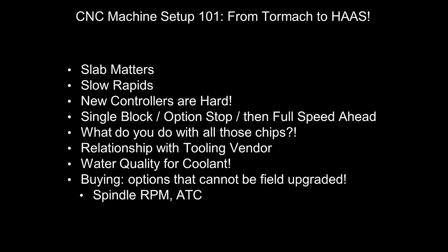But again, I'm very glad you brought up the work holding. People often forget how important it is and how easy it is to throw apart or pull a tool out of the collet chuck, all these sorts of things. Yeah, and that's kind of increase in power. That's kind of my overall theme. I mean, it was a necessary step, and I love the machine, but everything gets more complicated. It's all the more important to make sure your parts are deburred so you don't have a burr that prevents you from having a good work holding, or we'll get into more.